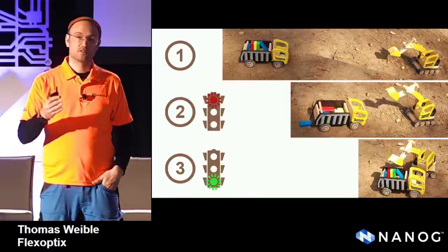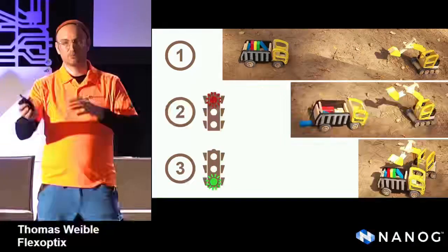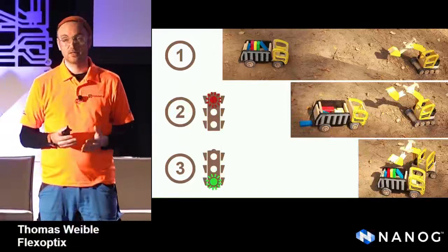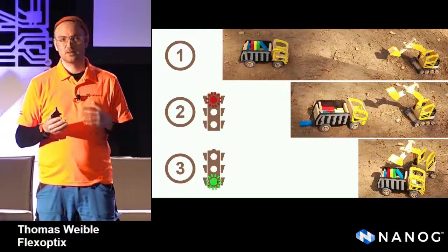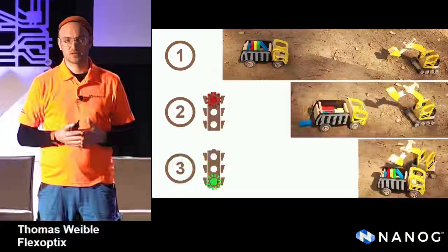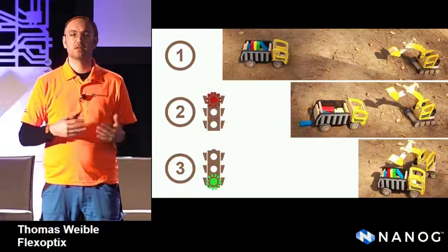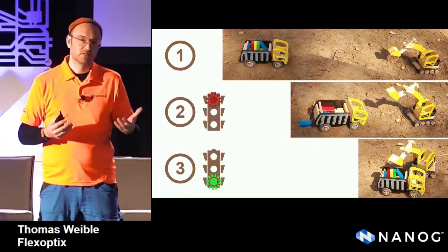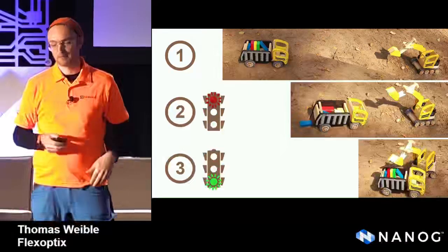Now you can imagine that this excavator takes a little bit of time to get all the bricks back in order and sort them, and also FEC needs time to operate. So in total you get an additional delay of around 100 nanoseconds on your 100 gigabit link when you enable the FEC there. That's something to bear in mind. So you need to give the FEC a little bit of time to operate.